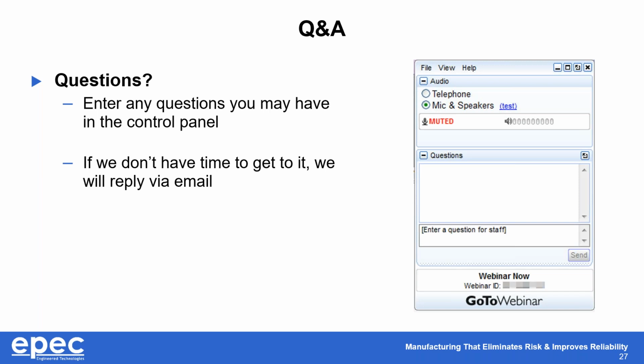Second question refers to controlled impedance. Given that achieving controlled impedance requires very specific dielectric thicknesses within the design, which then contribute to the thickness of the design, can controlled impedance be achieved by using thinner copper, thinner line widths, and thinner flex cores? And the challenge there is that there aren't any material thicknesses available that allow you to create a manufacturable construction.